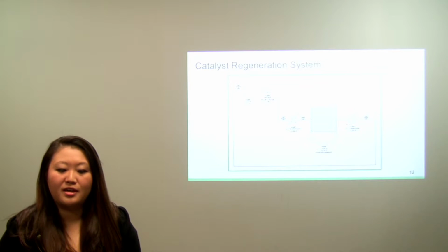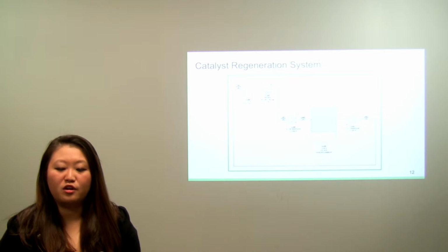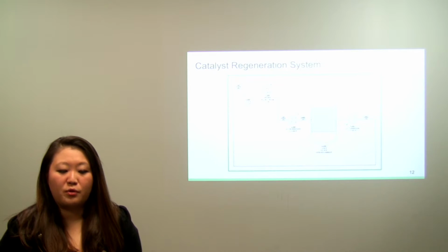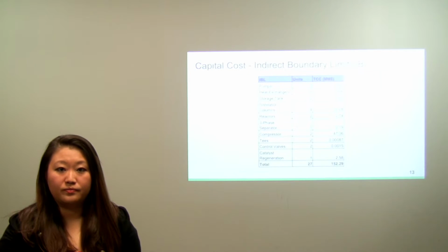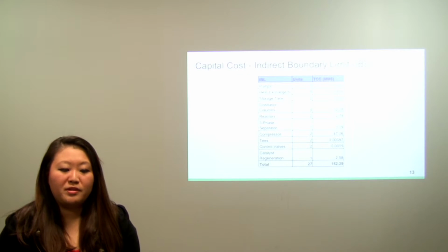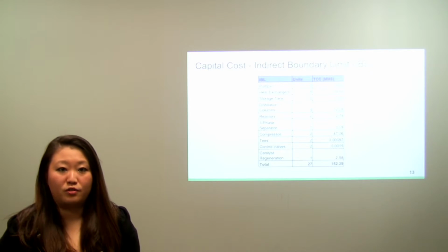Due to the flammability safety regulations, only 2 weight % maximum of oxygen is allowed in the steam and air mixture. It was determined that having an operating reactor and 100% spare reactor will be the most ideal to minimize the production downtime and the capital costs associated with catalyst regeneration after a careful economic analysis. The typical regeneration requires a fired heater, knockout drum, cooler, and a water pump. All the equipment listed here has different sizes, and of course individually they have all different costs.